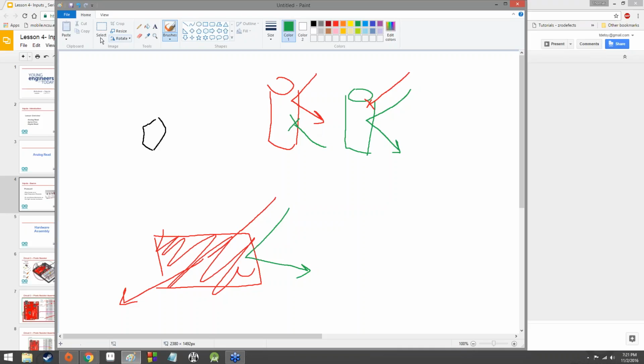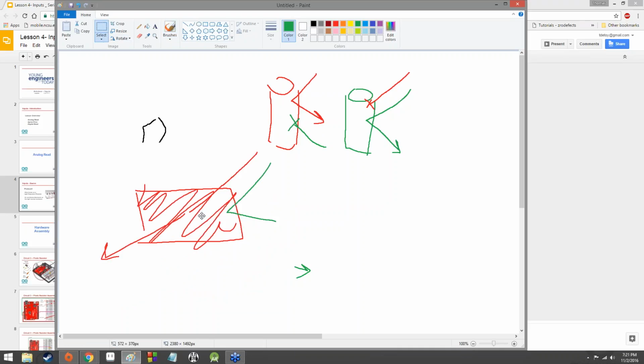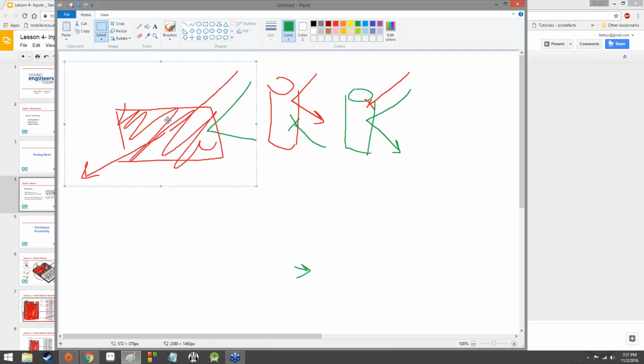So now, imagine we've taken our red cellophane, we've placed it over the LDR, and we shine white light onto a red peg. The red light is going to bounce off of it, and it's going to be able to go through the cellophane. If this were green, it would get absorbed, so there would be no green light going in.